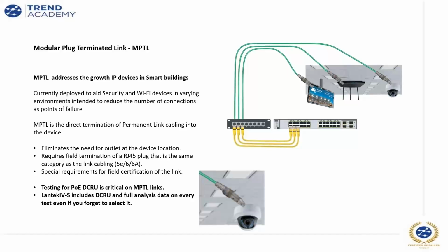Okay. So because of that, I'd always recommend investing in a high quality product wherever you can to mitigate against corrosion and challenges with good connections. It's imperative. And number two, you must do this test. So it's called MPTL, and it was designed by the standards exactly for this reason. The detail is modular plug terminated link.